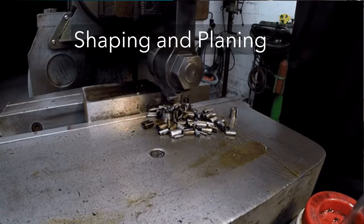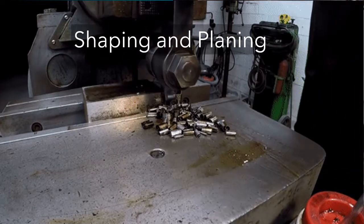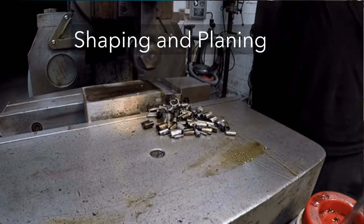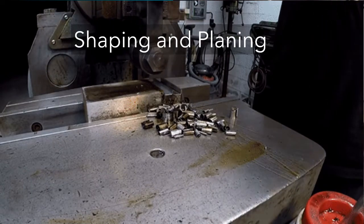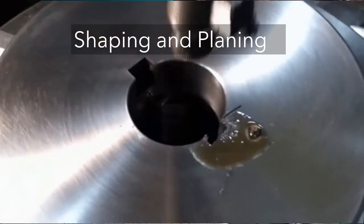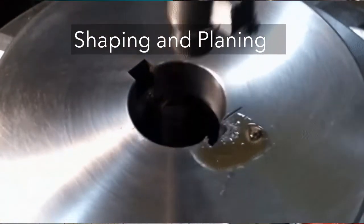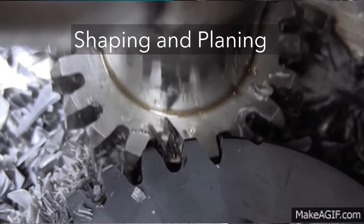Shaping and planing can be used to machine shapes other than flat surfaces. The restriction is that the cut surface must be straight. This will allow the cutting of grooves, slots, gear teeth, and other shapes. Special machines and tool geometries must be specified to cut some of these shapes. An important example is the gear shaper.